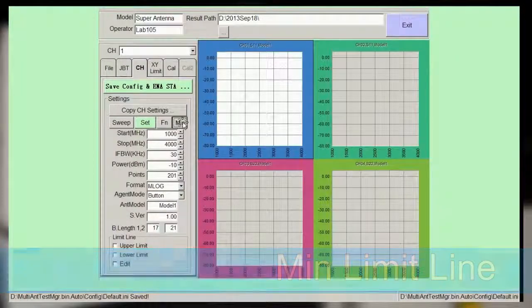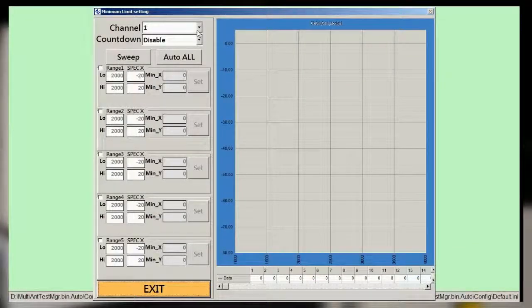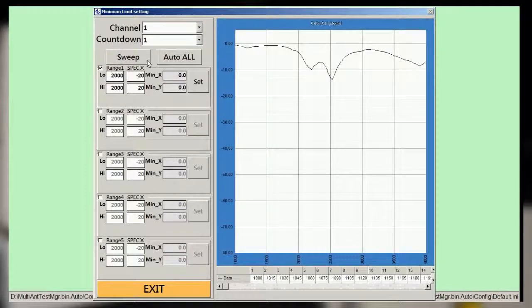Limit line minimum is for characterizing in-band frequency versus magnitude. First, have a gold sample swept, then move the cursor along the trace waveform; the corresponding frequency appears, giving an idea of the minimum magnitude data and frequency. Then set the in-band range and preferred magnitude.